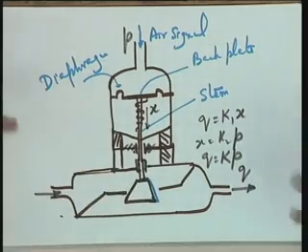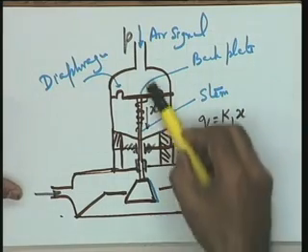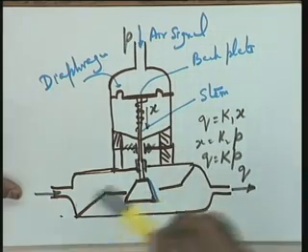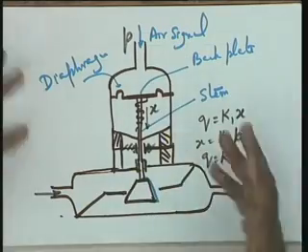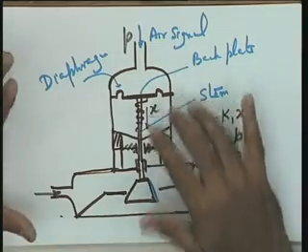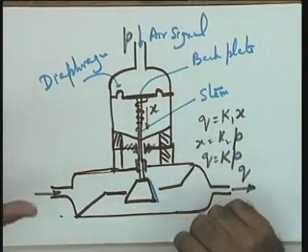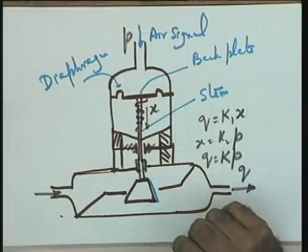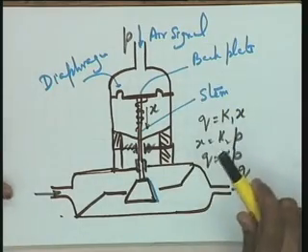The question which came to your mind that day was what is the load. Please see that the movement of this stem, rotary in that example and linear in this case, is itself a large load. In process control applications it requires large power, and this is the load which the electric motor was driving in that case, and in this case the pneumatic operated device is driving.